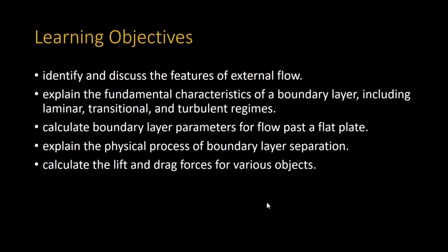After completing this chapter, you can identify and discuss the features of external flow, and then explain the fundamental characteristics of a boundary layer, including laminar, transitional, and turbulent regimes, and then calculate boundary layer parameters for flow past a flat plate. Explain the physical process of boundary layer separation. And in the last part, you can calculate the lift and drag force for various objects.